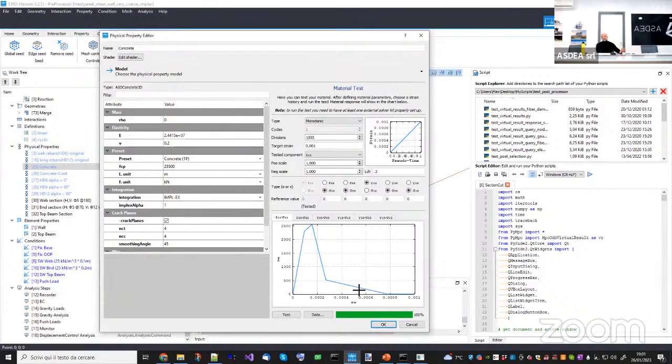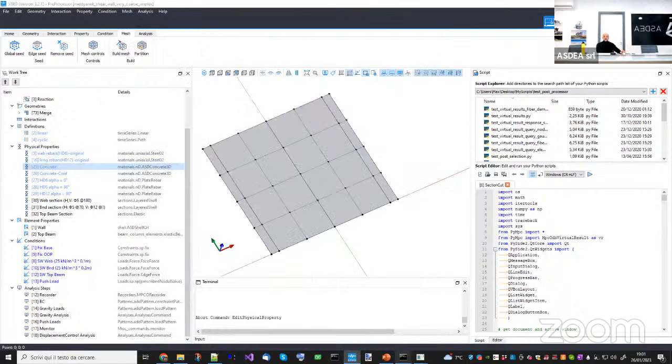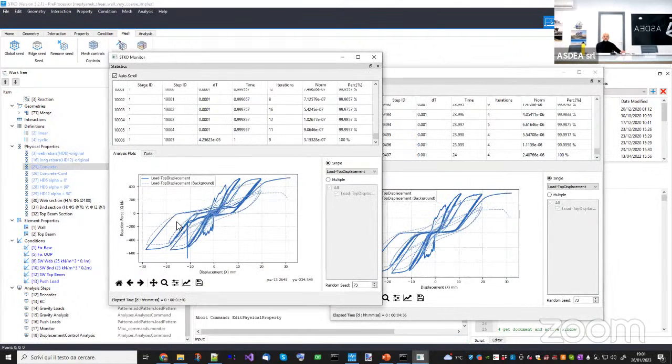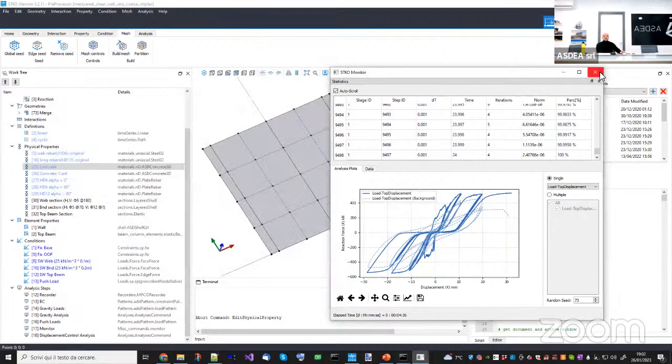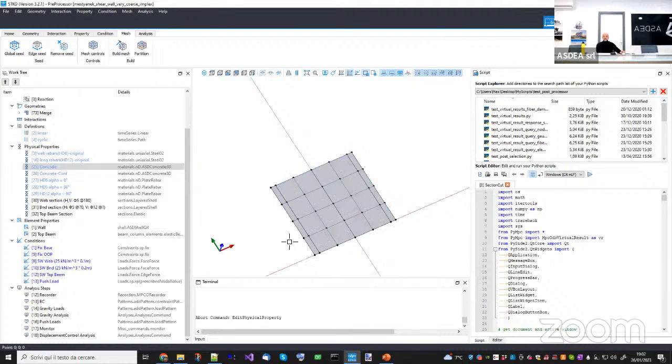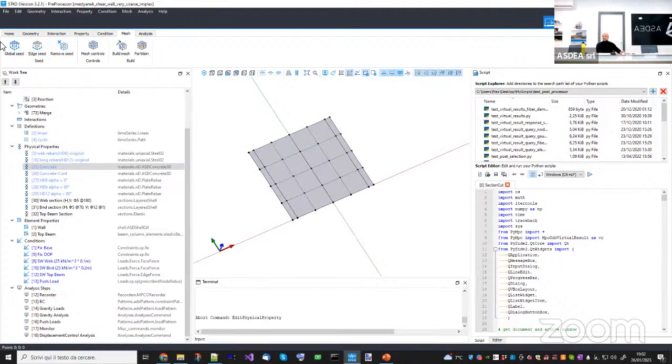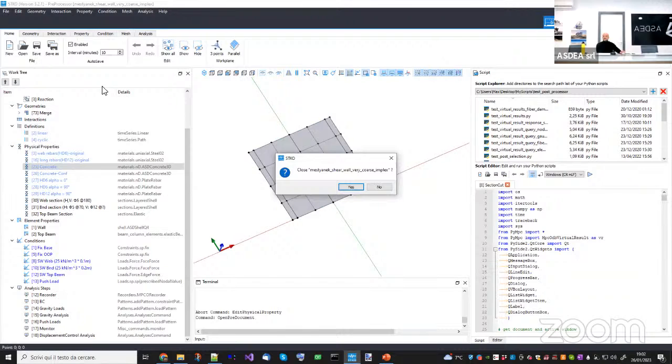So the only drawback that you have with a very coarse mesh is that you may encounter, especially with the IMPL-EX algorithm, some instabilities like this. But you will see that these instabilities will soon disappear as you refine the mesh a little bit. And then I will also talk about other settings for controlling the IMPL-EX algorithm. Now let's move on. This one was 0.6 meters, and we already had a good result.